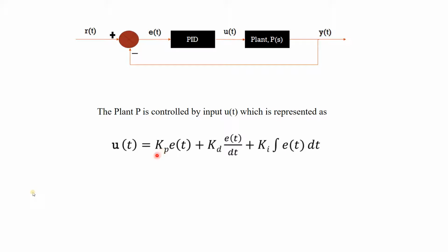The output which the PID controller is giving you is actually the summation of all the 3 controllers, which have acted individually on the error. That means the P controller will act on the error by its own method, the I controller will act on the error by its own method, and the D controller will act on the error by its own method.